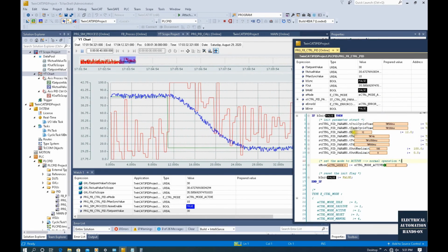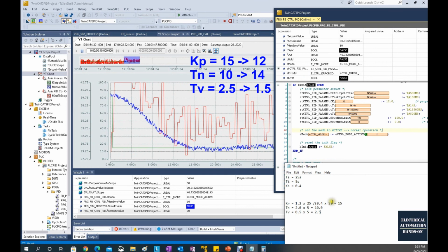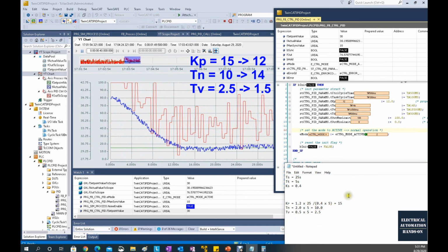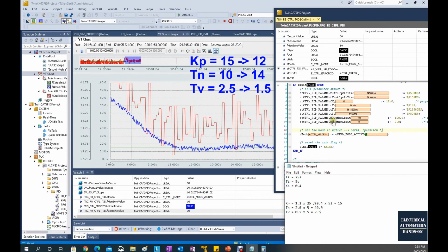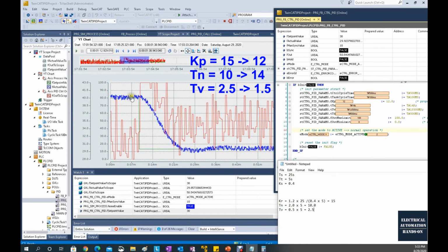This is the current PID parameters, and these PID parameters are based on the Ziegler's calculation, and this is just a quick fine-tune. We will see this dark blue, this is the actual process value. There's no obvious overshoot. The actual control performance shows pretty good actually. Based on this presetting, this pre-calculation from the Ziegler Nichols setting rule, we tuned a little bit, do a very quick commissioning. Process behavior shows very good. That means this Ziegler Nichols setting rule really works for this case.